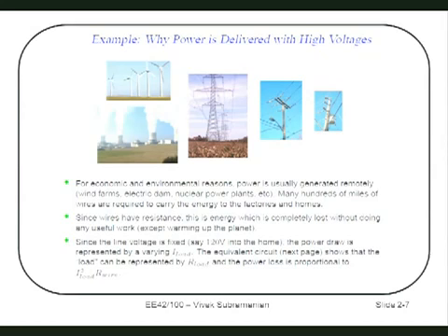Actually, it is somewhat related to safety, but it's more related to insulators. All insulators, it turns out, have a certain field at which they stop being insulators and become conductors. That's called the breakdown field. You've seen this: when you buy your plastic-coated wires, your extension cables, they are rated for a particular voltage. That rating limit comes not from the wire itself, but from the insulation on the wire. If you put too high a voltage on this cheap insulation that we use,